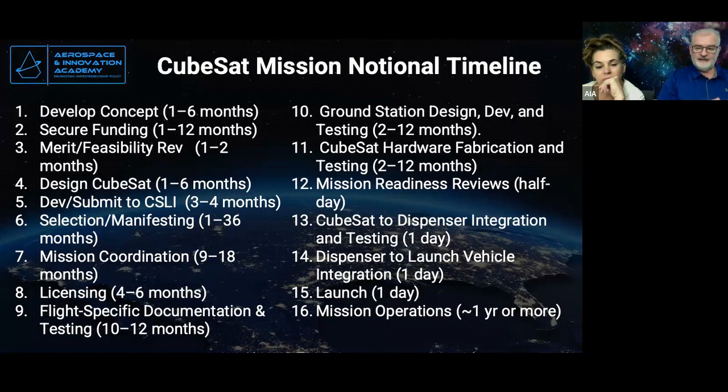And at the right time, you will send current through a resistor that is touching your fishing wire, and the fishing line will be melted, which will allow your components to deploy. There's always a chance for something to go wrong, and being redundant is just good engineering practice. So NASA recommends, and so do I, that you use redundant fishing lines or monofilament lines to hold down your deployables.